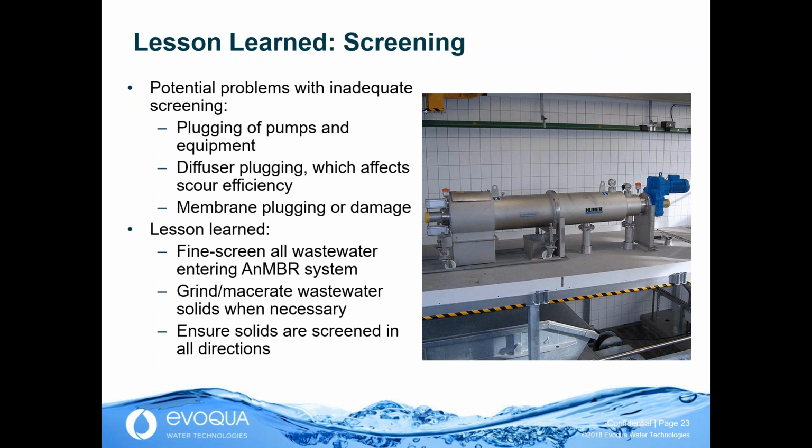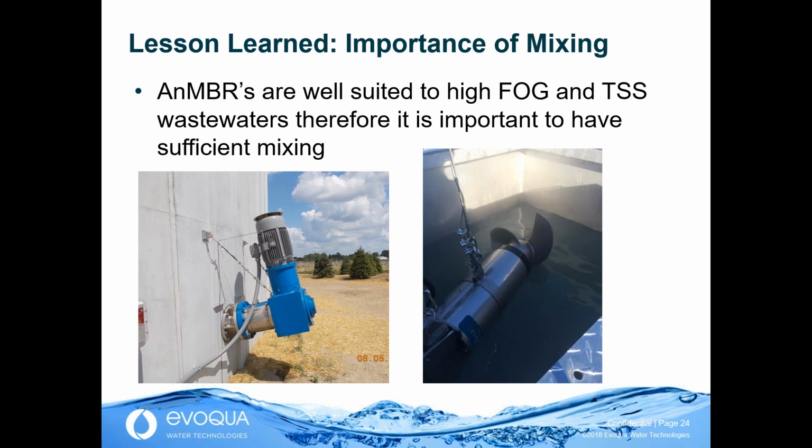Now, one difference with the anaerobic MBR, unlike most wastewater treatment technologies, is that we may not simply want to remove large particles, as these represent potential biogas for the system. So we may want these solids to be fed to the system. We just need to make sure they're broken down to an acceptable size before we feed them to the system. Either way, having well-screened wastewater makes the system a lot easier to operate.